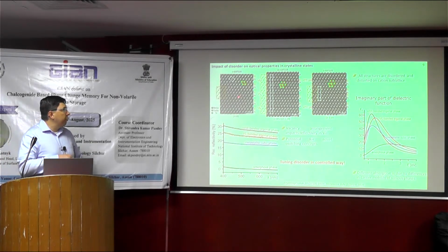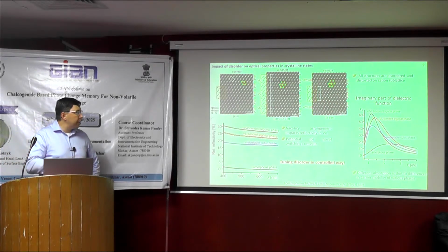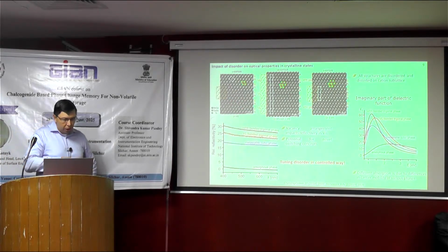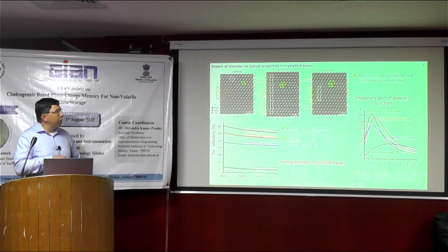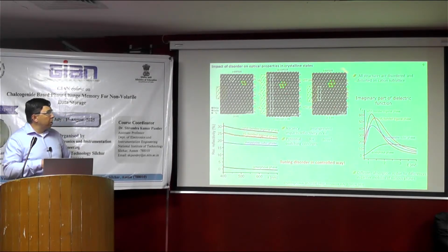As I said, especially in the crystalline phases, phase change materials like GST225 have three different crystalline phases. One is highly disordered. One is a more ordered phase consisting of van der Waals-like gaps. And this phase, in between, contains a high number of vacancies on cation sublattices, up to 20%, which can then be ordered, here shown as these dark lines. So we can get different structures. They were grown as epitaxial thin films.